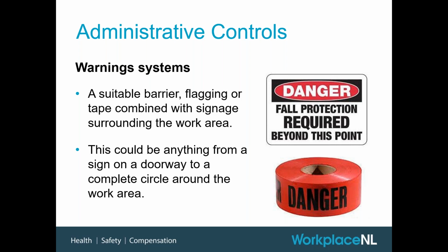And there was a bit of a kerfuffle as far as what that guardrail was supposed to do. A guardrail has to be set up to prevent a person from leaning, pushing, or falling on it. Short of climbing it or overreaching through the edges, that guardrail should prevent someone from falling into that area.